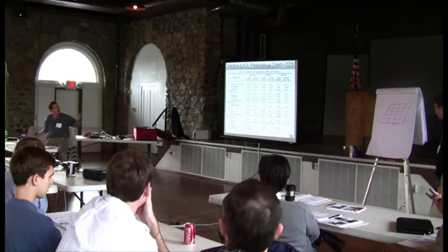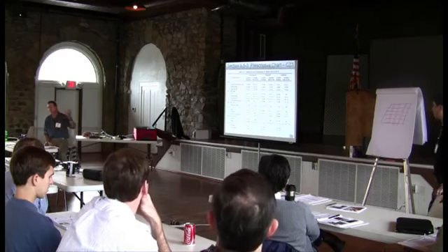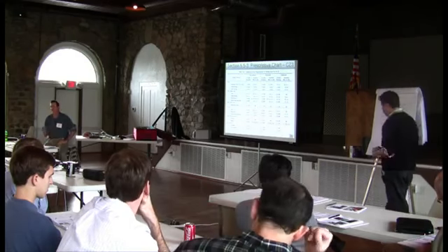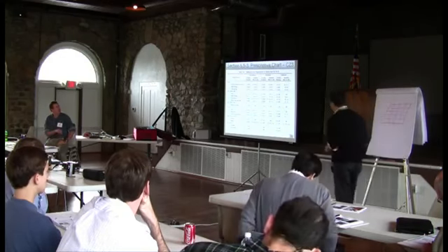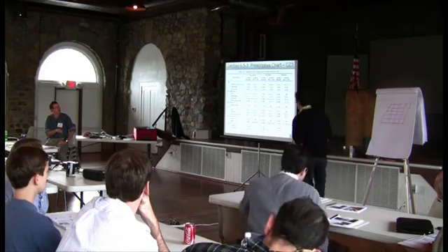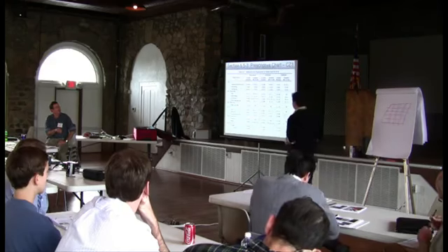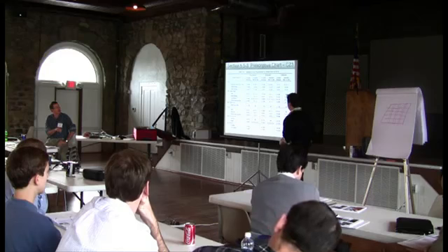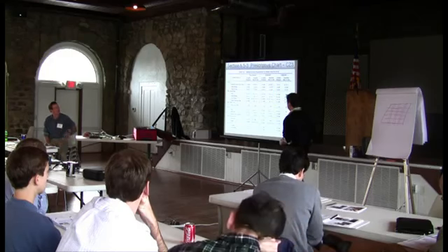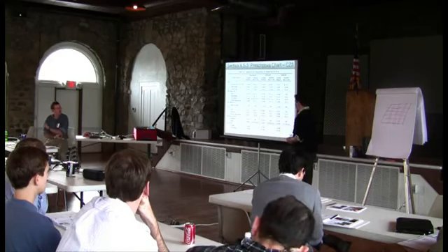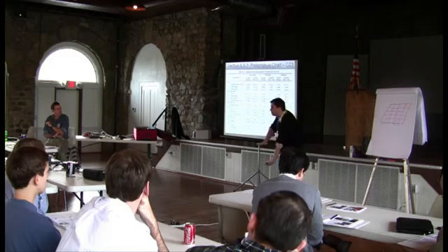Okay, next on the list, a wall below grade is a basement wall. You do not have to insulate that wall in this climate zone. A floor is typically, if you frame it, about R19, so similar to a residential, or if it's a mass floor, about an R6. So again, when we're talking about these floors, this is a floor that has a space under it.